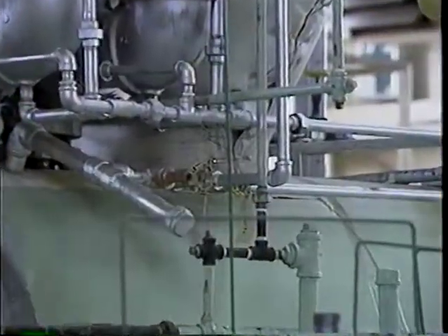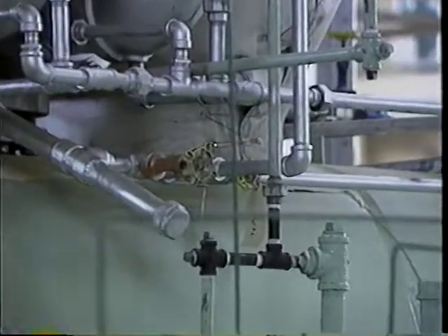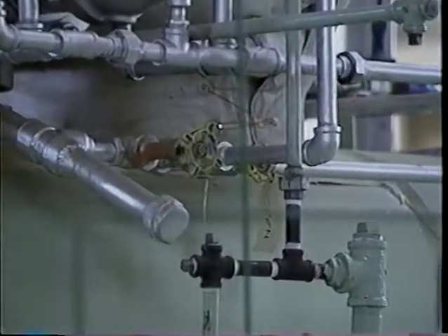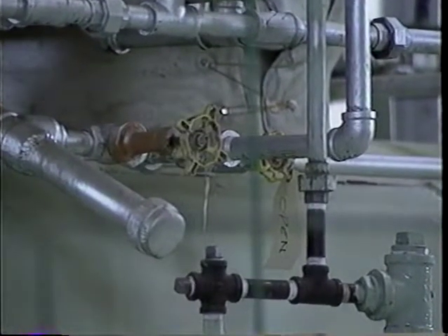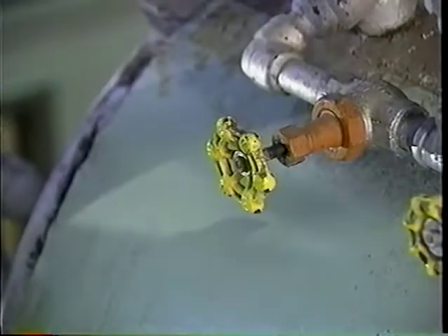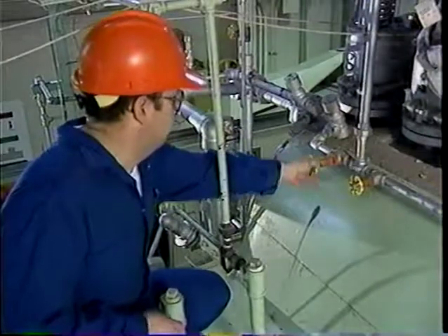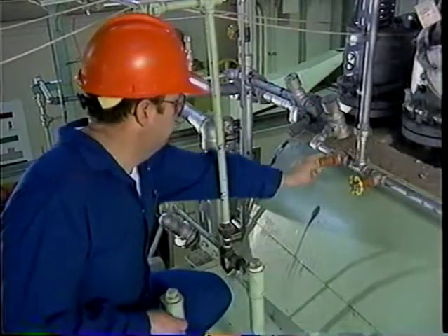The globe valve controls the flow of steam passing under the valve seat through the valve. This change in direction causes a decrease in steam pressure. A globe valve decreases steam flow and can be used to vary the amount of steam flow. It should never be used as a main steam stop valve.